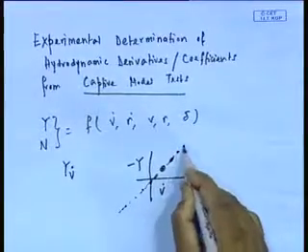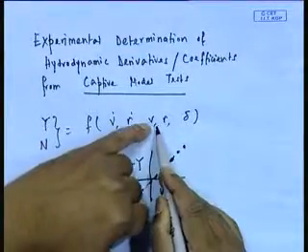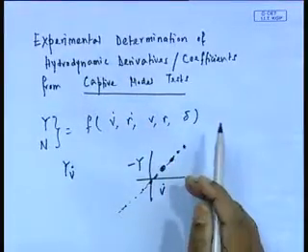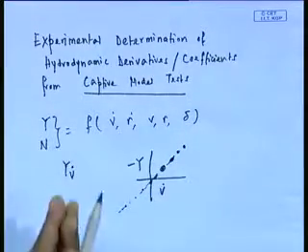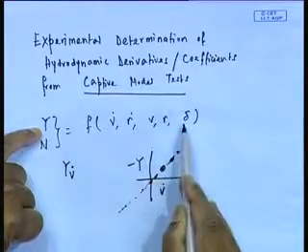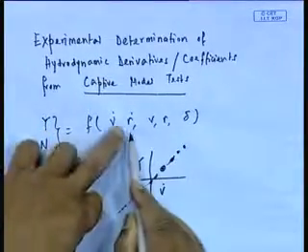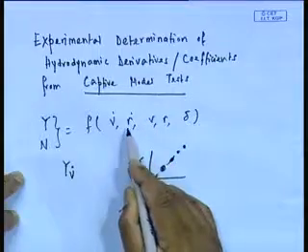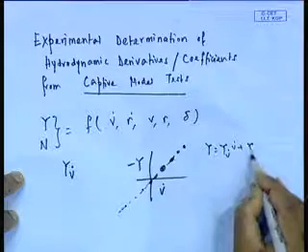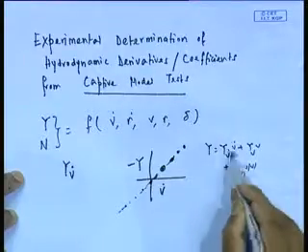I need to measure experimentally what Y force is coming because of v dot, or whichever parameter. What about the other parameters? They should be 0, not a straight line, they should be 0. So, this is the fundamental requirement: when I want to measure Y against one parameter, all others must be 0. Otherwise, the force I measure would also come from the other parameters. For example, if both v dot and v are there, then what I measure would be Y_v dot plus Y_v. So, you see, how do I isolate them?